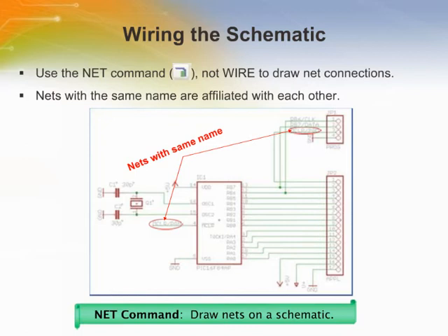You might think that you'd use the wire command to make connections in your circuit. However, a wire in Eagle is just a line. To properly make actual electrical connections, you need to use the net command. Nets will automatically form junctions when terminated on pins or other nets. Once you've clicked the net button, your mouse pointer becomes a drawing tool. Click on a pin, or anywhere actually, move your mouse somewhere else and you'll see a line, or net.